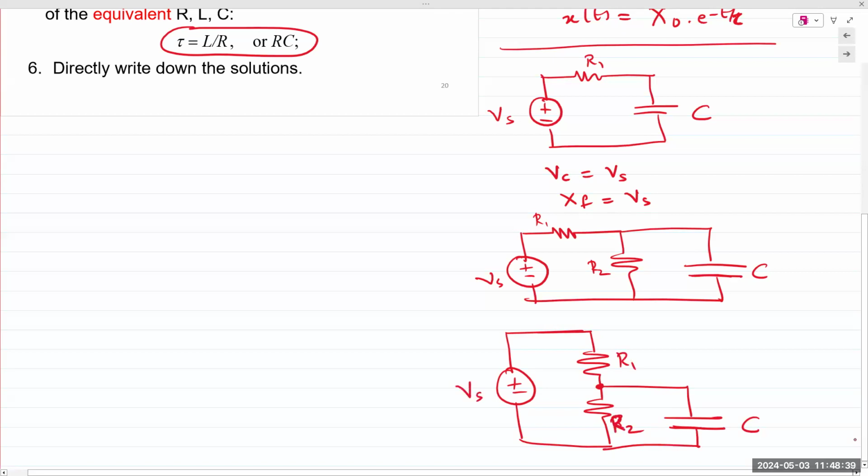If the capacitor C was not there, what happens to the voltage Vs? It splits between R1 and R2. Right? When is the capacitor not present in the circuit? When it behaves like an open circuit, which is when it reaches full charge. That capacitor voltage will be equal to the resistor voltage across R2 because they're in parallel. So that's another way of looking at it. It reaches full charge, becomes like an open circuit, and everything flows through those resistors. Voltage is divided across R1 and R2, so Vs is not being applied directly to that capacitor.